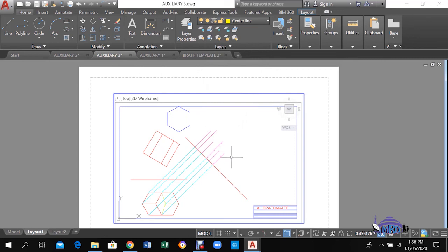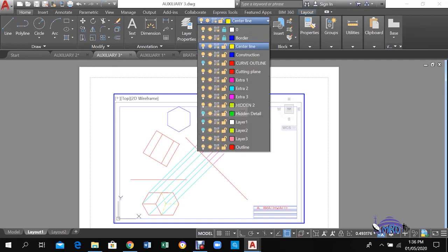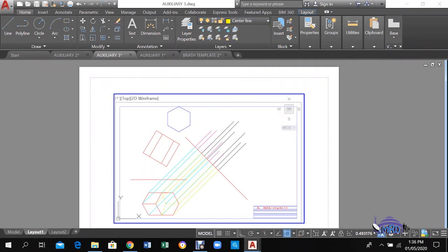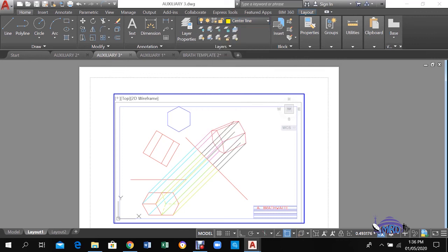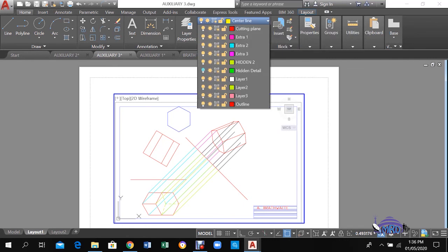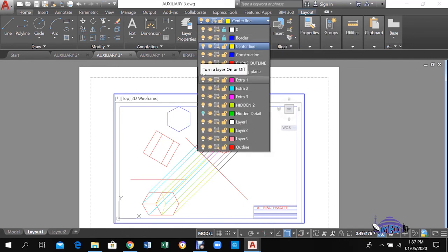Now I'm going to drop back in the first set of lines as well, so it can look a little confused, but then we will make sense of it at the end. So all of those projection lines now will show you this. You might not see it now, but there are actually two hexagons represented here. So you would then have to plot those two hexagons, connect those corners, and your drawing would then look something like this. So you can see now the hexagon for the bottom, and you can also see the hexagon for the top.